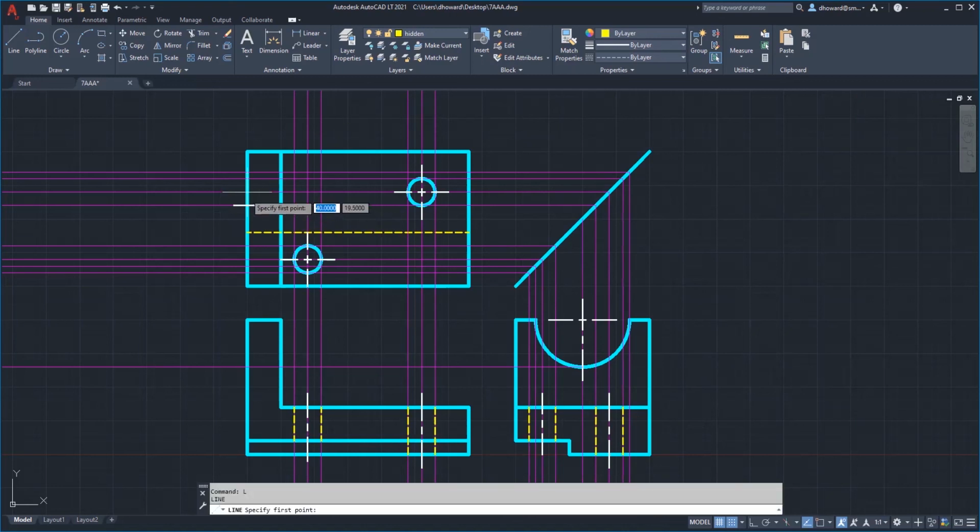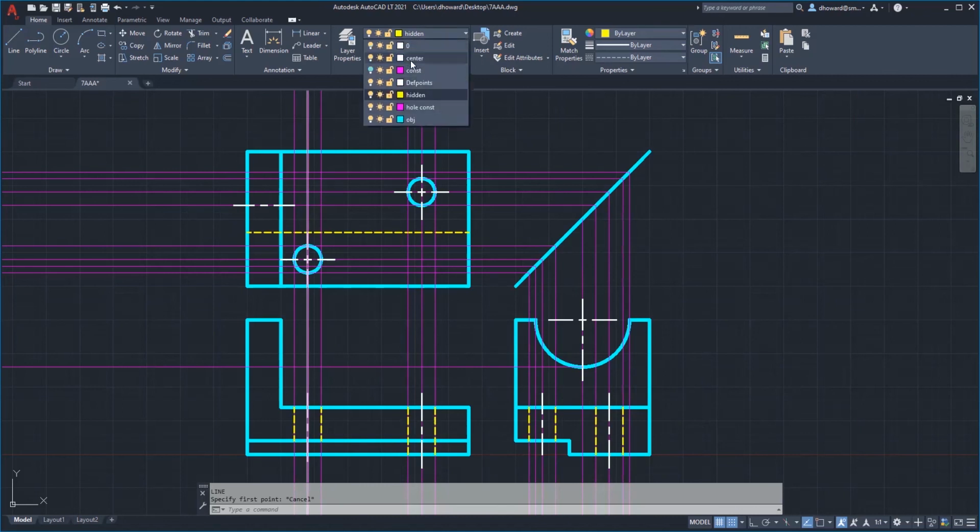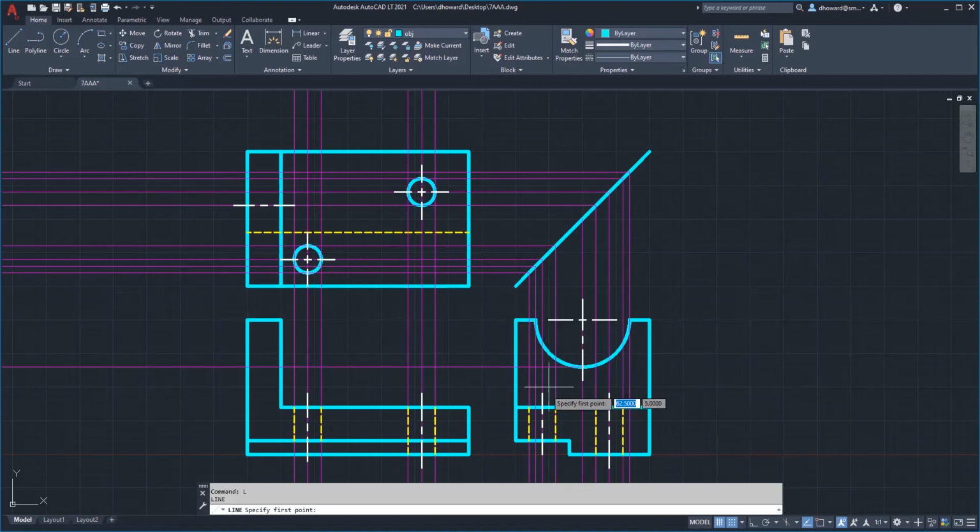Go up to the top view and do the sides of the arc. And that's just regular object lines, because they're not hidden. You can clearly see those edges, and they are from here to here. And from there to there.